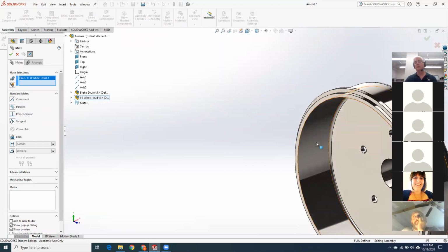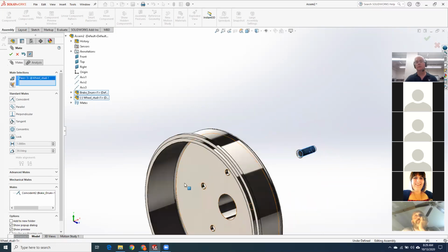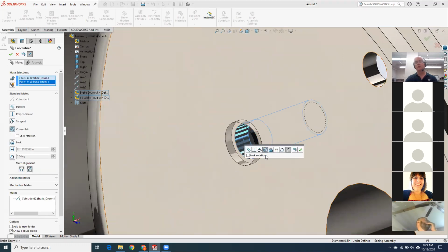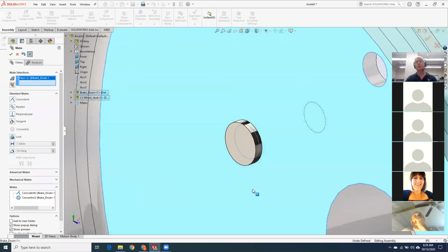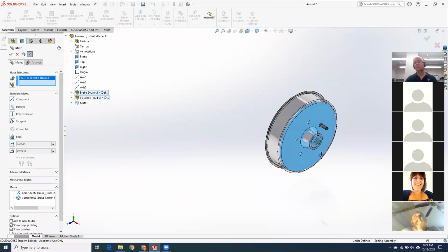And in the real world, we come up with a big pressing tool, and we press those two faces together. Okay, so that's going to give us the correct distance going into the part. But now we also need to put it in the hole. And that's where a concentric is a perfect mate. So now I have the shoulder up against the back face of the drum, and the threaded rods are sticking out.